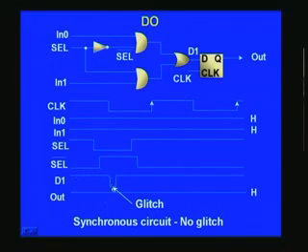It's precisely this, and this is caused because you can just see here, this is 1 and this is 0. So being an OR, 1 plus 0, or the other way, is going to be 1, just as here also, 0 1. So all through it will be 1, except for a small interval here. At this portion it is 0 here, and it is also 0 here. So this 0 will produce 0 right at D1, and that is how you get a glitch here, and this is contributed by this inverter. It's the propagation delay of the inverter which is responsible for creating this.